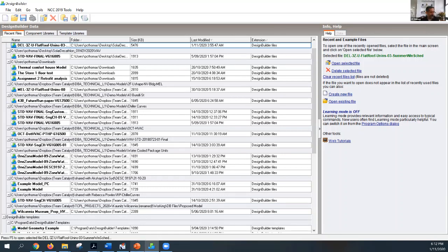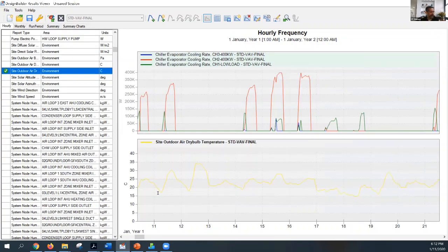What I can say is that if you take this ESO file, what I was showing you, once you select a series of variables that you're interested in, you can save only these variables onto a CSV file, which you can open in Excel and do post-processing. So you can pick up all the variables that are used to generate that adaptive number that you're looking for, and then post-process that for each zone.